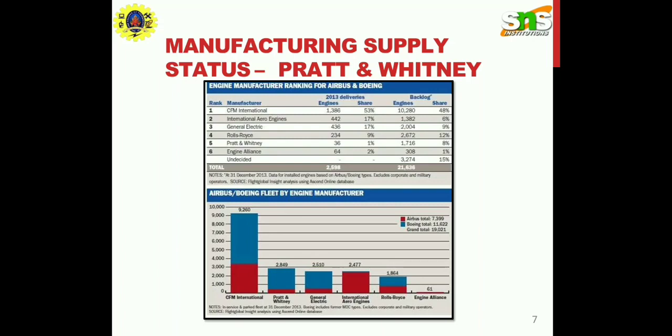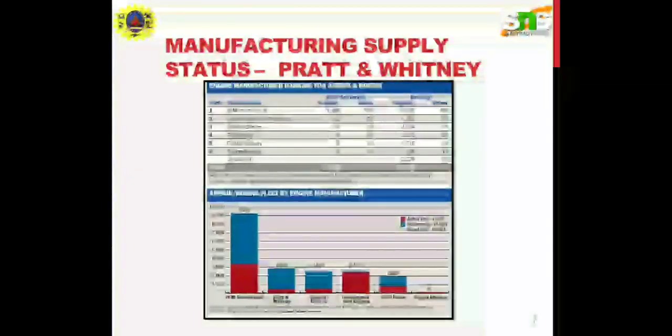Turbo machines can finally be classified by the pressure changes across the blade. Impulse turbo machines operate by accelerating and changing the flow direction of fluid through a stationary nozzle, and the nozzle serves to change the incoming pressure into velocity. The enthalpy of the fluid decreases as the velocity increases, and the pressure and enthalpy drop over the rotor blade is minimal. Velocity will decrease over the rotor. A Pelton wheel is an impulse design.